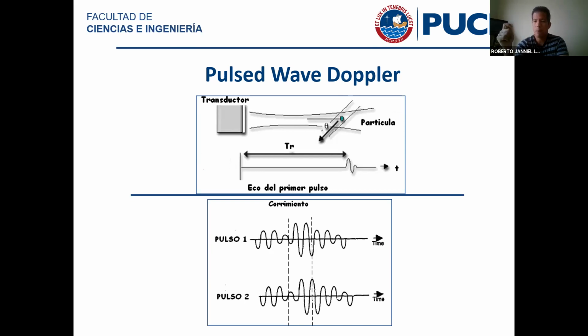So there's a shift of 1 microsecond, and I can relate that to how much the particle was supposed to be moving. And because you have the amount of time that it took in between those two transmissions, you can translate that shift into an actual velocity of the particle, right? Because the time you can change into distance, and you know the time in between your two measurements, so you can calculate the velocity because it's just distance divided by time. Yes, David, I think you have a question.